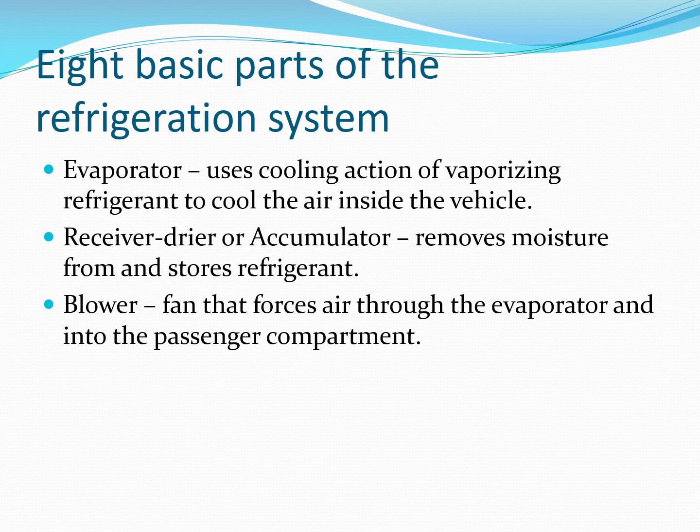If we need to make that air, say, a little drier, we might add some air from the heater core to dry that air. There's going to be times when maybe the air coming out of that vent is too cold. Well, you can move the dial or move the slide on the dashboard, or in some late model cars, move the button that increases the temperature, and that is going to change the airflow from that blower fan. It might be blowing over the heater core or a combination of the heater core and evaporator at the same time to blend the temperatures to get the desired air coming out of the vent that the driver wants.